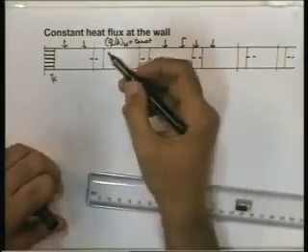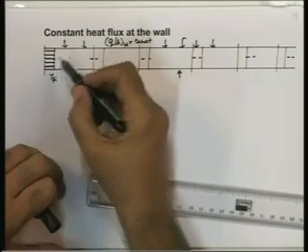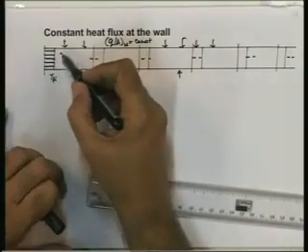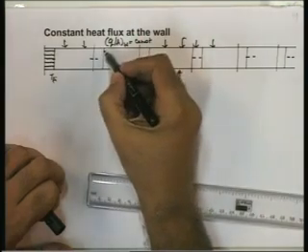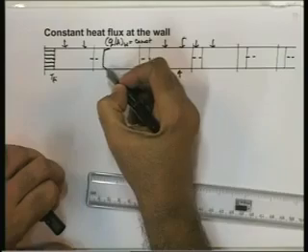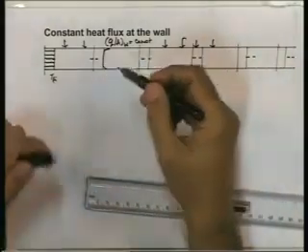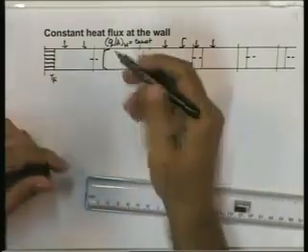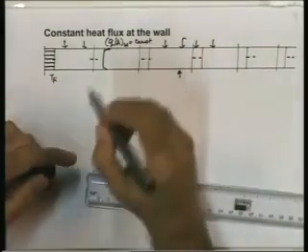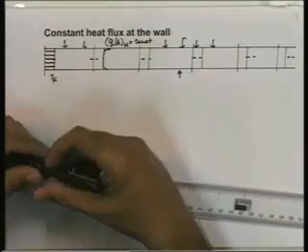But now there is a heat flux, so the fluid gets heated up, and first the lamina of the fluid near the wall would get heated up. So we'll have a profile something like this. Notice that the heat flux at the wall would dictate the temperature gradient at the wall, dT by dr, because k into dT by dr would be equal to the heat flux in magnitude by Fourier's law.